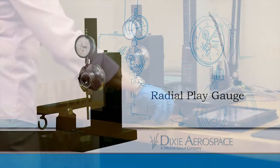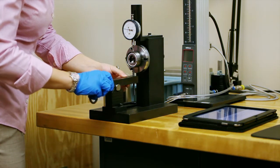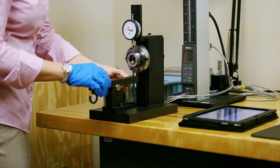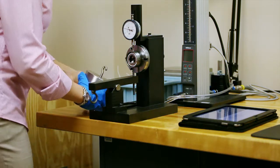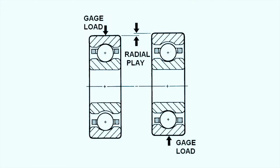The radial plate gauge was designed and manufactured by Dixie to measure the looseness that exists between the rolling elements and raceways. This clearance is a critical part of how the bearing will operate in the design system. The engineers will choose from a variety of calibrated weights depending on the size of the bearing. In this example, we're using an 11-pound weight. As the weight is placed on the rocker arm, it is transferred to a radial load on the outer ring. The dial indicator reads this radial play as the space between the inner raceway, outer raceway, and rolling elements as the weight is applied.